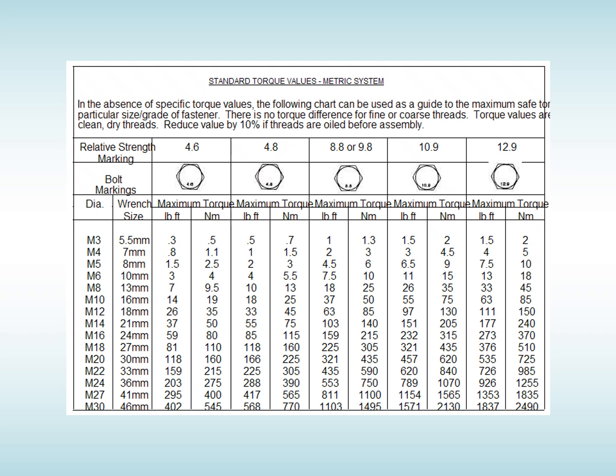Well, how do we know how tight to tighten a bolt? Well, you can look up a chart like this. It gives you the different grades of tensile steel, and it gives you the diameters. So all we do is, for example, look along an M10. It tells you the head size and then the different torque settings for the different grades of bolts.